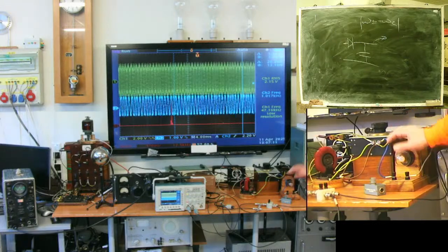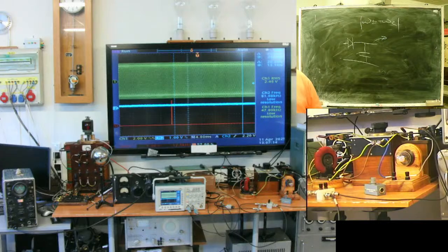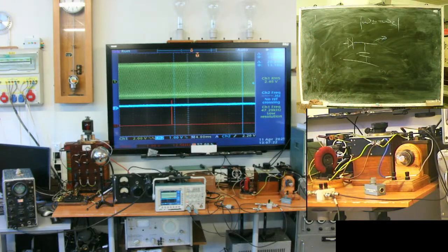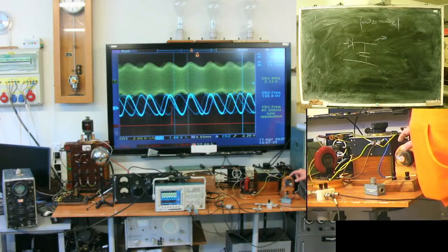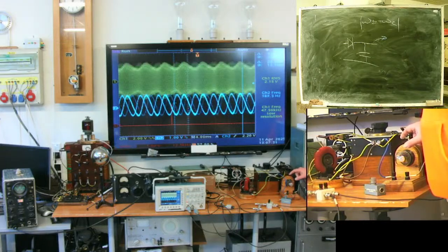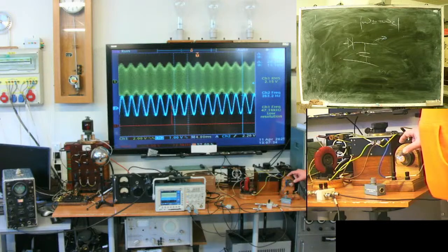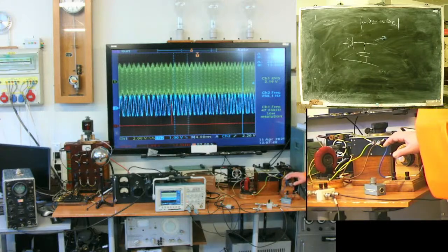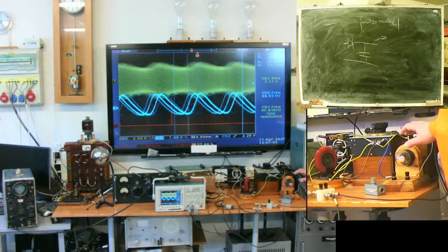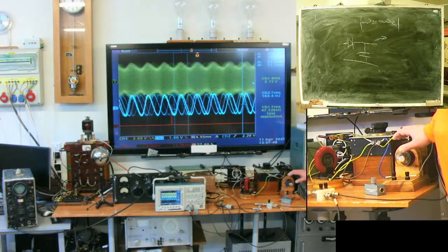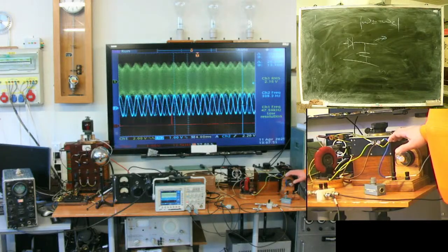So, the bigger the difference between omega 1 and omega 2, the higher the frequency of the difference. I'm talking about this blue line. Yeah, the blue line is near harmonic. It's not ideal, because the bigger the difference, the higher the frequency. Distortion is non-linearity. At low difference, I have theoretically higher distortion, because my circuits are not ideal.